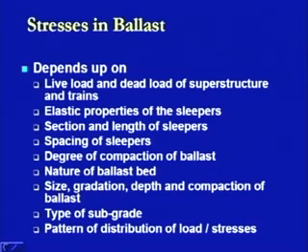The degree of compaction of ballast is another area, because in the case of the ballast, most of the time we are using a type of material where the load is going to be transferred through the points of contact of that material. Say we are using stone aggregates. Because of the contact of those stone aggregates, the load will get transferred. So, if the degree of compaction is good, the transfer will be there. If the degree of compaction is not good, then there are going to be deflections and more stresses of that nature.